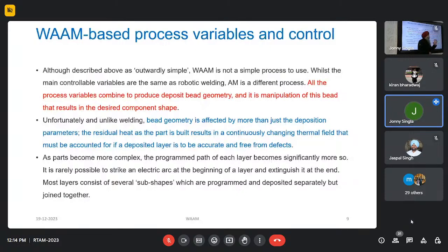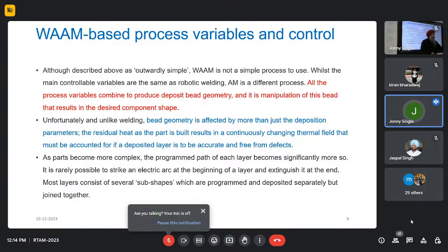Nothing has gone wrong with the quality of the component. Everything was fine, radiographic quality was there, dense parts were there, no porosity issues, no deformations. But the only issue was that the residual stresses could not be maintained below a certain level. So that is one vicious character of the residual stresses which needs to be looked into.